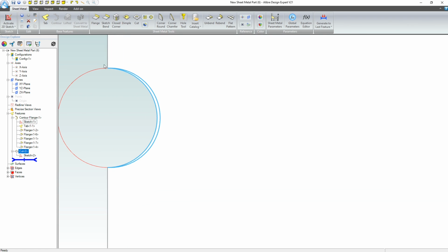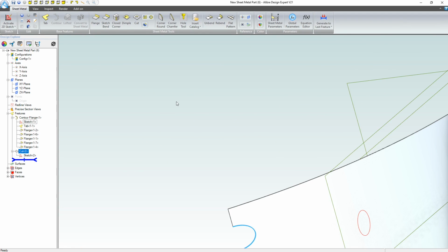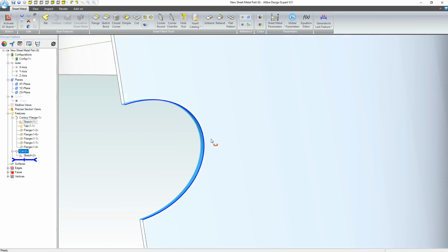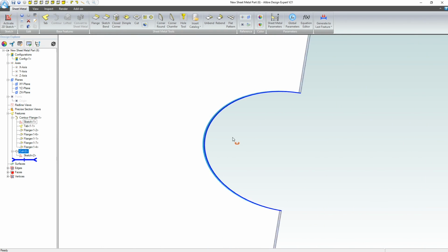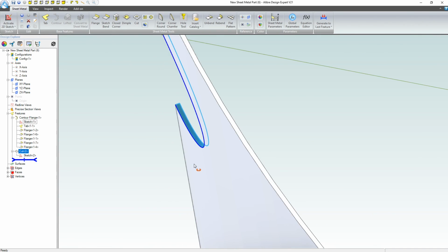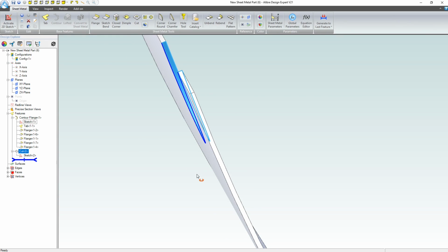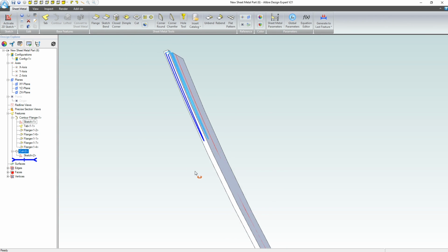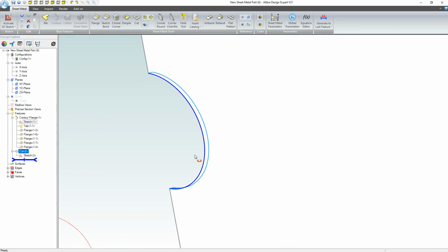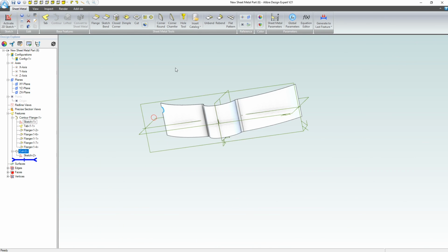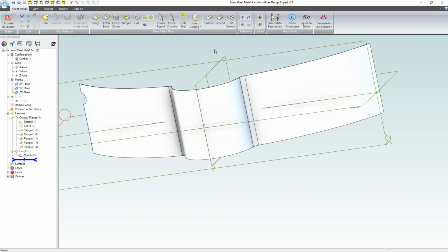And you can see that we have two sort of arcs here, and that's because it has adjusted the cut for the curvature of the sheet metal. So it's not like you have a straight through cut, like a straight through, extruded cut. You actually have a cut that stays with the profile of the sheet metal, which would reflect this being cut in the flat before it was bent. I think that's a really cool feature. You don't get that with other platforms, and I think it's a cool way to deal with it.